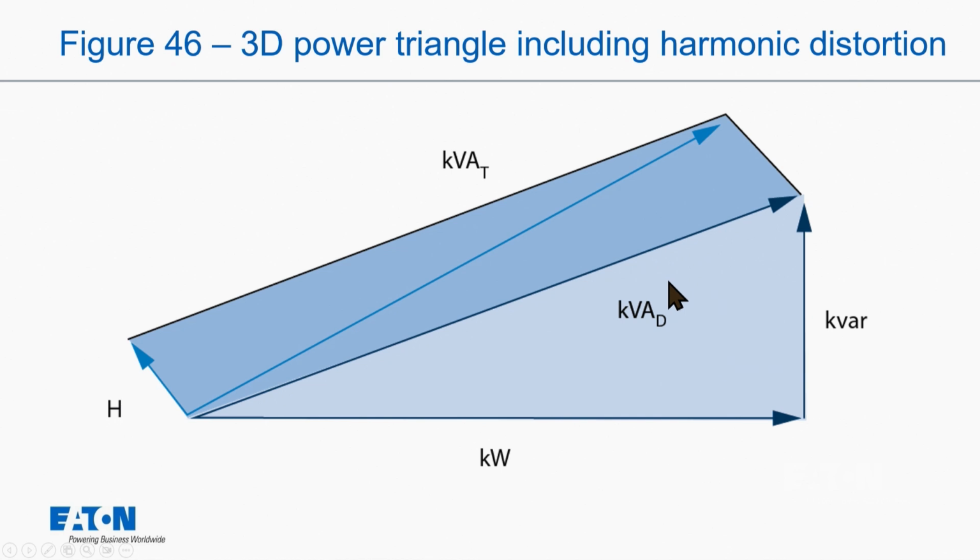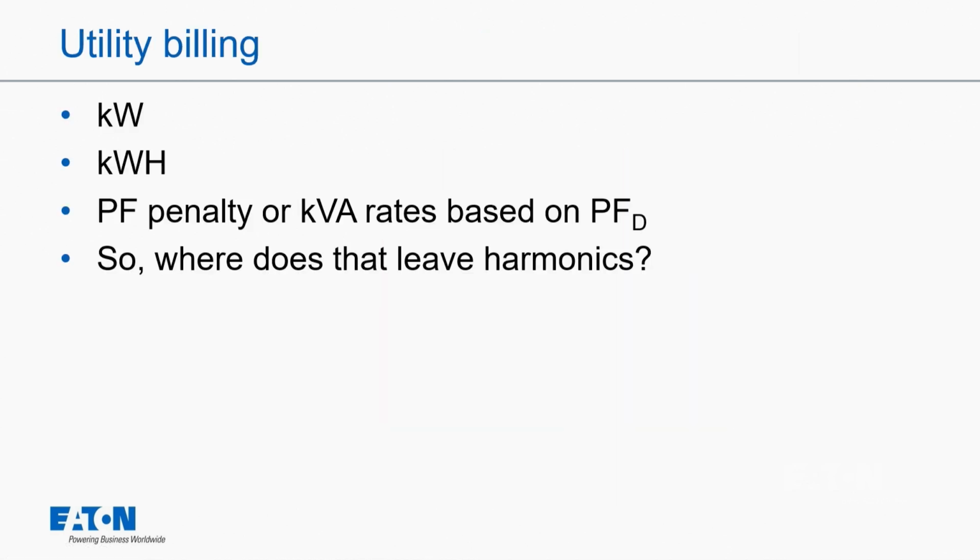And that's really important to understand, because what do we pay for on our bill? On our bill, we pay for kilowatts, or the amount of power that we're using. And for commercial customers or large industrials, we pay a kilowatt demand. And there's lots of information in our videos about that. There's kilowatt hours, which is basically kilowatts over time. So these two are directly related.